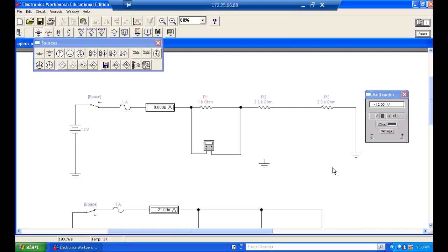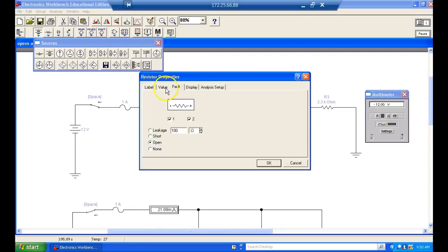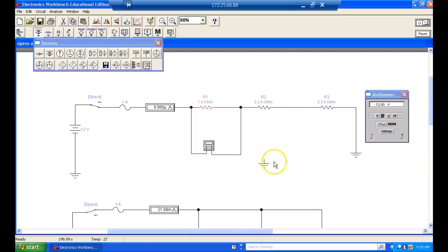So we'll prove that. So we'll come over here. Let's write these down. So this guy right here, I'm going to take the fault out of this one, and we can do the math. I'm going to set no fault. Okay, I'm going to turn the simulation back on. And notice it's dropping 1.85 volts. Let's write that down. 1.85 volts.